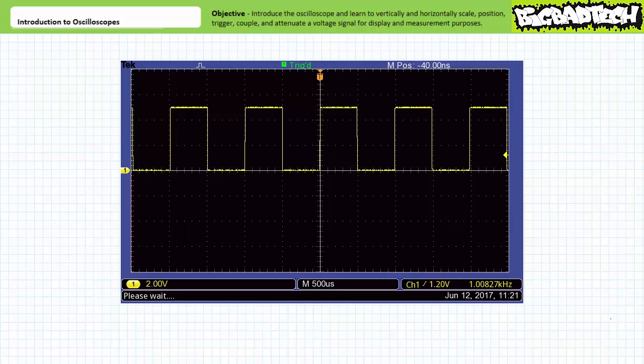As long as the triggering event regularly occurs, the oscilloscope regularly samples the waveform and spits out data. For our sample test waveform, triggering at 1.2 volts going positive would mean the oscilloscope establishes roughly the first quarter rising edge of our pulse as our 1 beat. Every time the scope hits the 1 beat, the oscilloscope captures the window of data and displays it on the screen. Given our waveform is periodic or repetitive in nature, establishing a particular 1 beat isn't all that important.